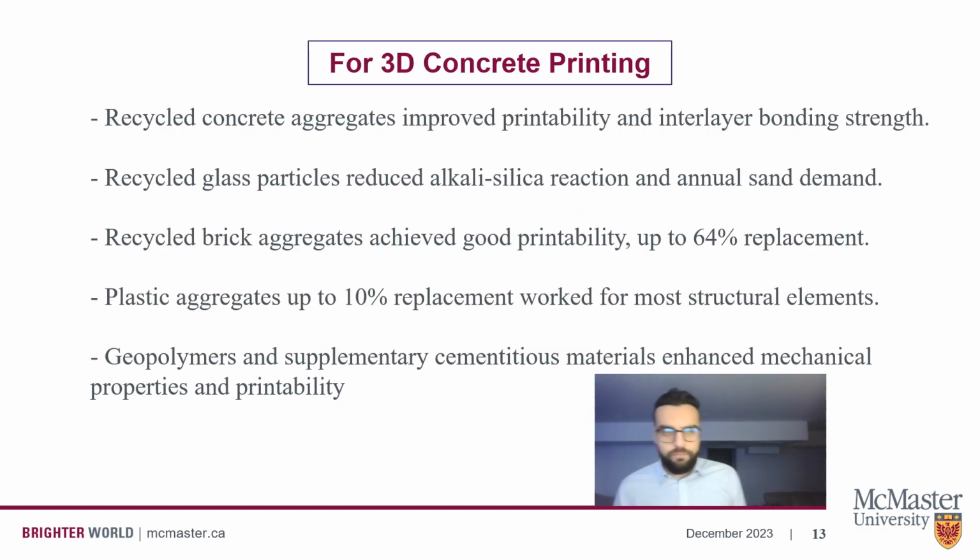So for 3D concrete printing, for example, we discovered that recycled concrete aggregates can improve printability and interlayer bond strength. The standard practice was just using cement and fine particles with a little bit of admixtures and water. However, again, we are trying to reduce as much as we can the quantities of cement in our mixture. So here, as you can see, the recycled concrete aggregates can improve the printability and interlayer bond strength. The recycled glass particles can reduce the alkali-silica reaction. The recycled brick aggregates can achieve good printability up to 64% replacement. You can imagine a 64% reduction of cement.